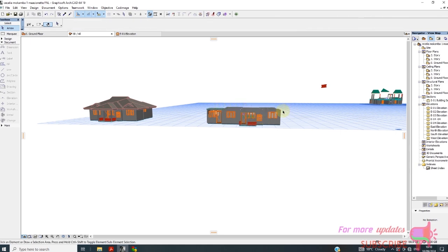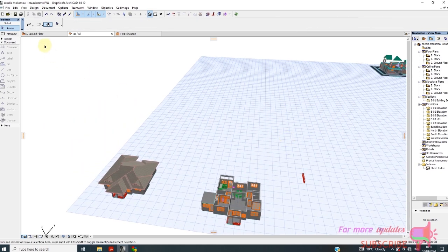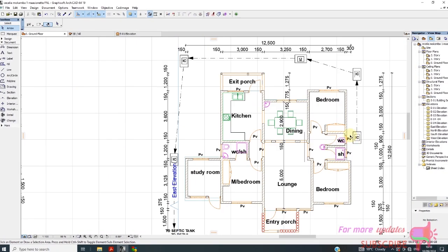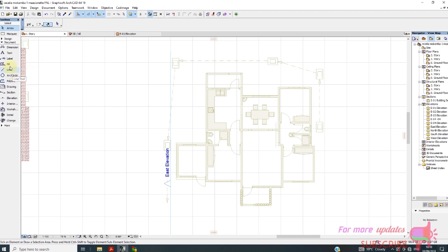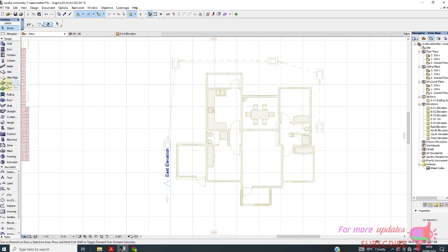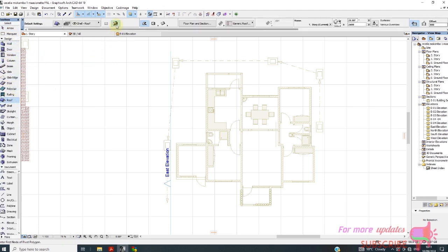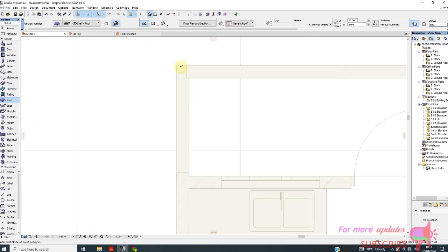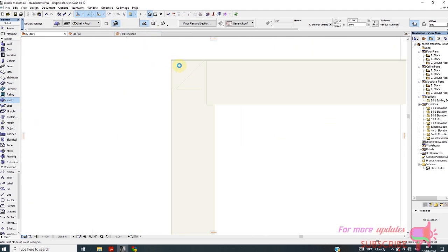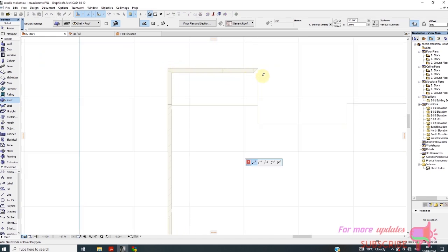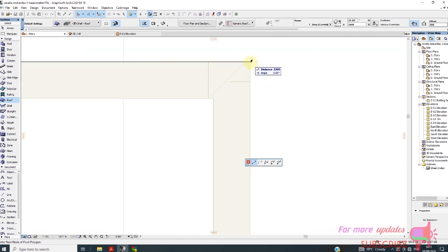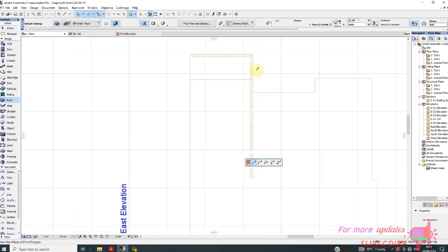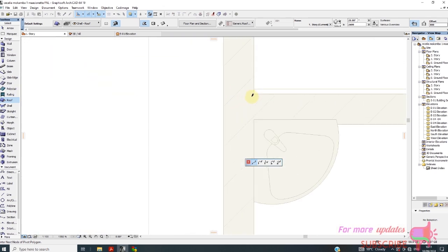Delete. All right. So I'll just go to the ground floor and show and trace reference. Then I'll go to story one. I'll go to design, activate roof, the first multiplane, and then this first option complex, so that we can quickly draw that complex roof from that point. You just need to pick the corners, all the corners back to the original.